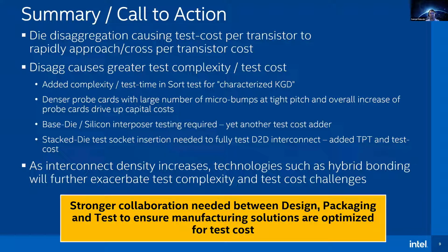Because of that, and related to that, I mean, you can't always test. If you have a failure to bond a certain number of signals or grounds on microbumps or hybrid bonding, you may not see that at test, but you might have signal integrity issues. Are there methodologies for detecting those?